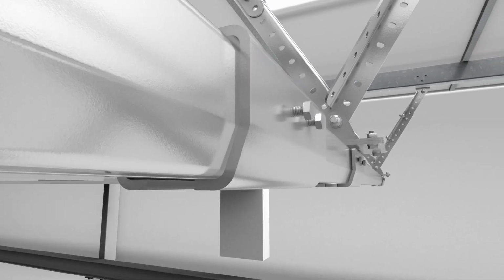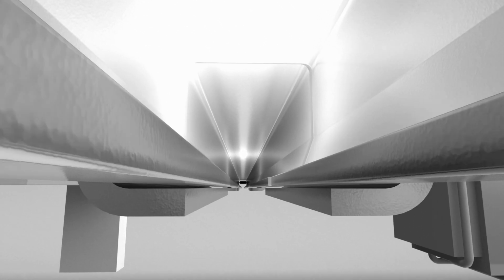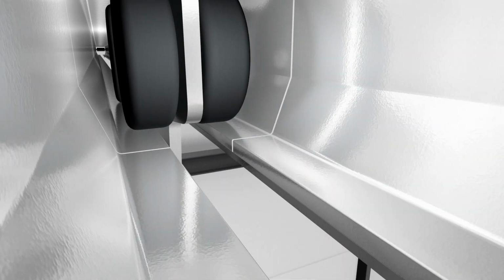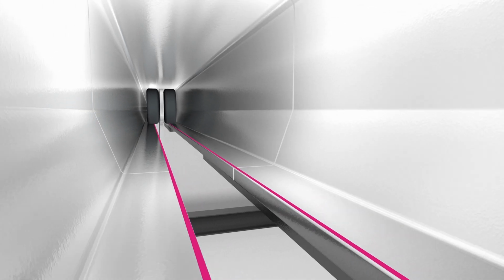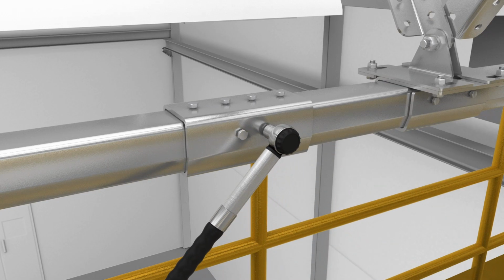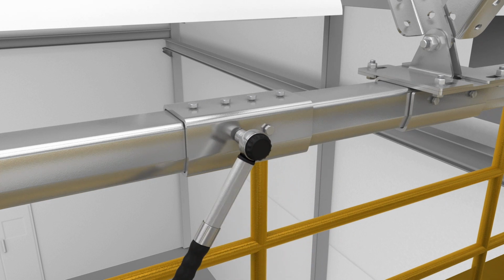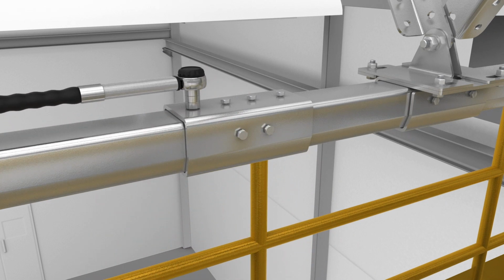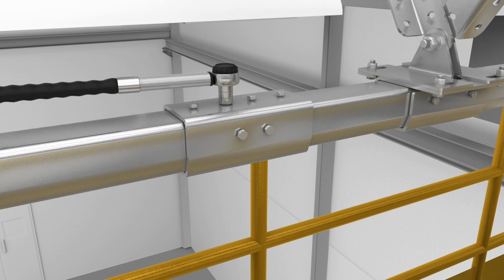To finalize the rigid rail connection, the 8 individual pinch bolts should be used to manipulate the position of both sections of rigid rail within the rail splice. To ensure smooth trolley operation, it is imperative that the adjoining faces of both rigid rails are completely flush with one another, and the rail sits centrally within the rail splice. Finally, tighten all pinch bolts to the torque value shown in the torque settings table.